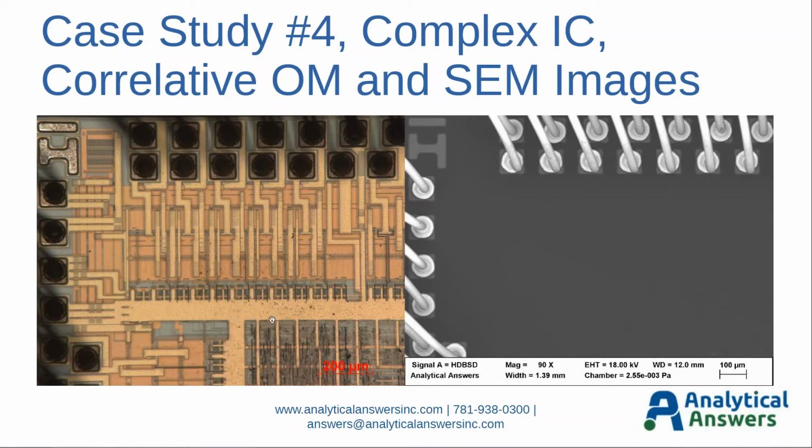So we're able to remove the component encapsulant material to expose the integrated circuit itself, to then examine it for potential anomalies or defects. And again, with correlative optical microscopy and SEM imaging, we can see that it yields different information about the sample itself.